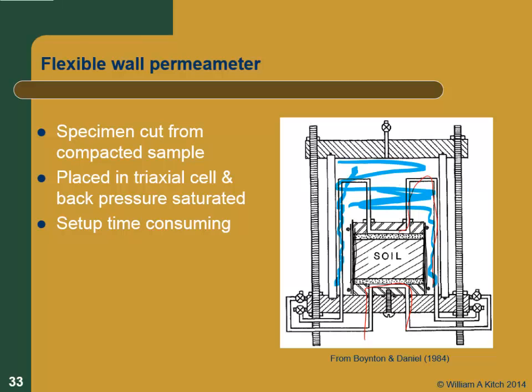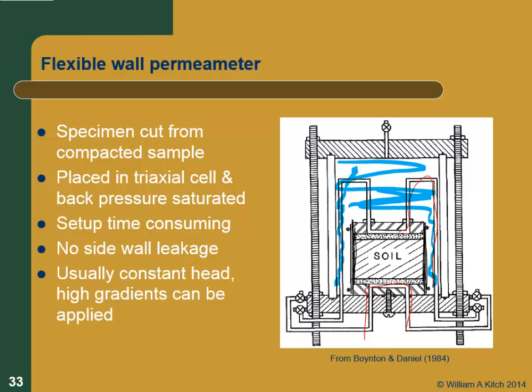It does take a lot longer to set up than almost any of the other tests, because you've got to basically set up a triaxial test, and you've got to back pressure saturate it. Sidewall leakage isn't an issue. And we basically don't have to run falling head tests anymore. We almost run these as constant head tests. And you've got complete control of the stresses. So this has become, by far, I think, the most popular way to do it. It's the one where you have the best control of what's going on.